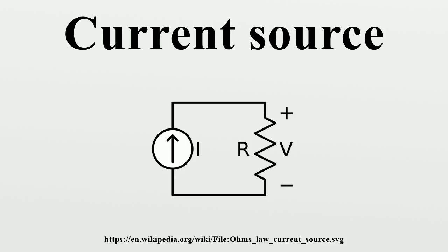Voltage regulator current sources. The general negative feedback arrangement can be implemented by an IC voltage regulator. As with the bare emitter follower and the precise op-amp follower above, it keeps up a constant voltage drop across a constant resistor, so a constant current flows through the resistor and the load. The LED is on when the voltage across the load exceeds 1.8 V. The grounded load is an important advantage of this solution.